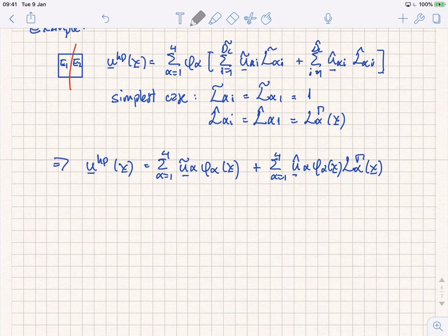It's linear. It's the GFEM. It's the standard part of the approximation. Right? And the second term is the one that contains the enrichment with the appropriate behavior that we're trying to reproduce. Yeah? So again, going back to what we discussed before we started, everything we do in this class is to extend our standard basis functions, right? The standard part of the finite element space, we augment that with enrichment functions.